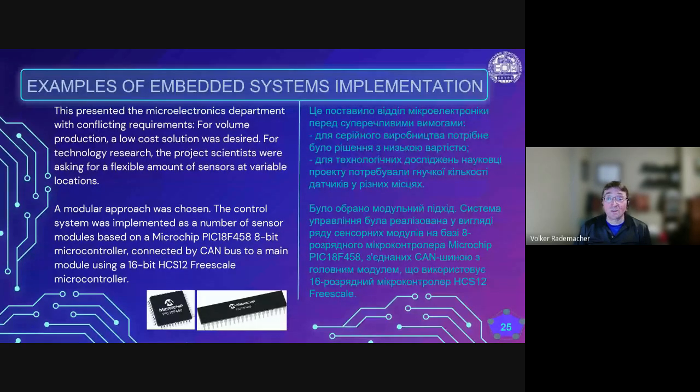So if it is detected that a packet has been corrupted, the same packet will be asked for automatically without the microcontroller having to do anything. So by the time the message arrives at the microcontroller, the designer can be assured that the data integrity is a given.